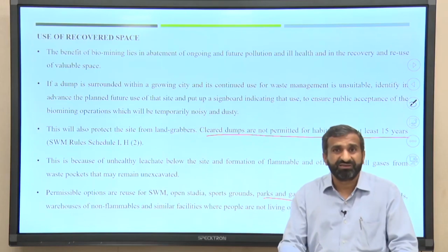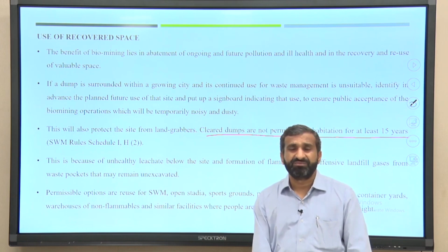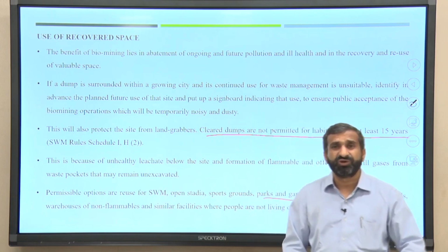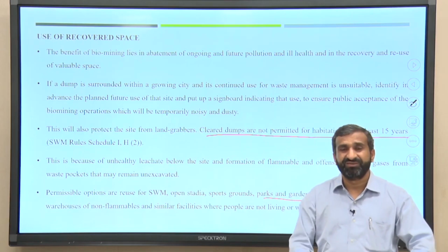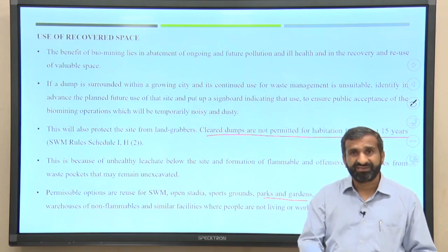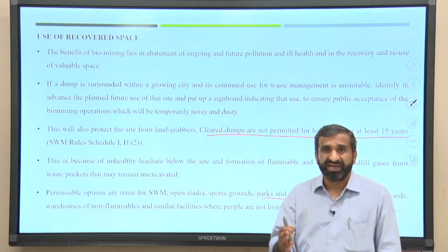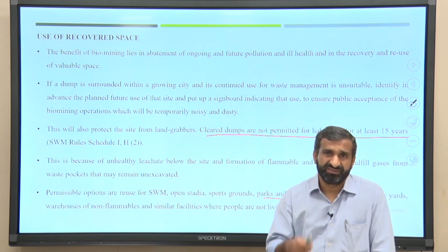Maybe a park is the best idea, or you can make a garden. But for the initial period, do not allow local people in that garden, wait at least 5 years, and from time to time collect gas samples and also check the groundwater.